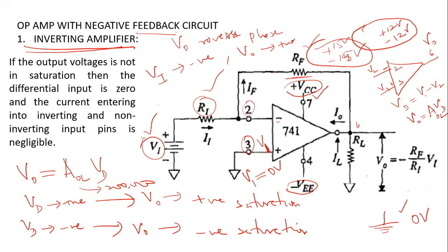But now if you have this feedback circuit, let's say you are giving a certain voltage signal to this input through this inverting terminal, pin number 2. And now if you're looking at this formula, VD is equal to V1 minus V2, and V1 being 0, you will find that your VD will be negative. If VD is negative, it will drive the output to negative saturation.